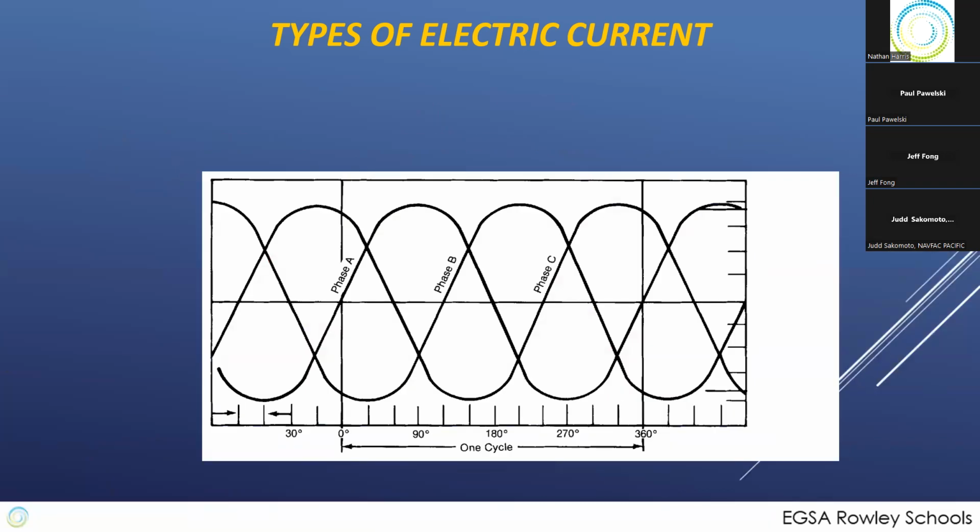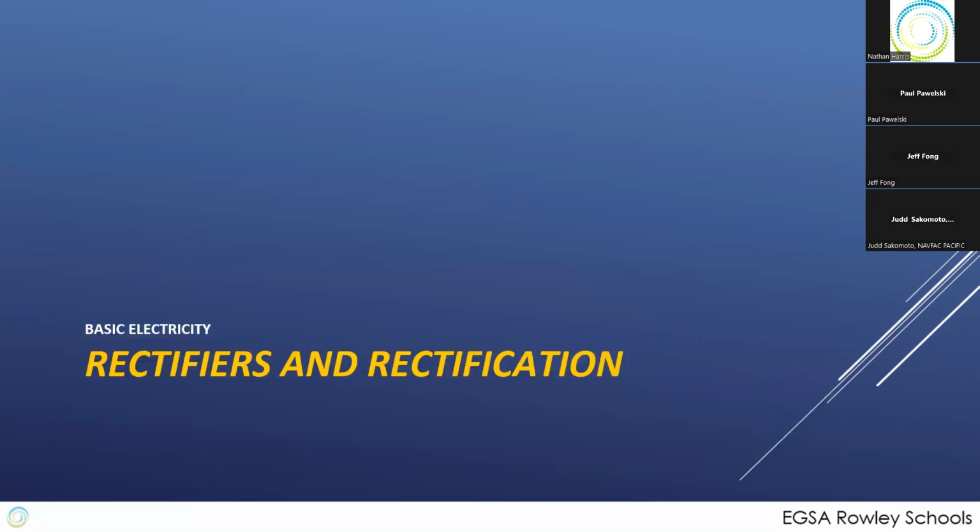All right, so looking at 3-phase, this is what we see. We've got 3 different phases. Each of them is a third of a cycle out of phase with the other 2. This means that we get peaks more often. This means that if we are using something that runs all 3 of these phases, we never have a situation where the load itself is experiencing 0 volts or 0 amps. This is very beneficial in keeping a lot of things running a lot smoother.